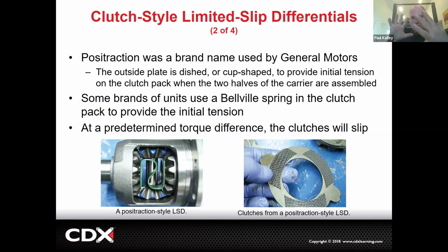The reason it was shuddering was the clutch discs were sticking because the wrong oil was used, or maybe because there was some clutch material and gunky debris, right? So they would stick and slip and shudder. Okay. So if you use the wrong oil, those clutches are going to tend to slip. That's why they have a friction modifier. They're going to try to stick, slip, and cause some shudder. If they stick and then slip, they're wearing out. So they're wearing prematurely. Okay. So that's why we have the additive.